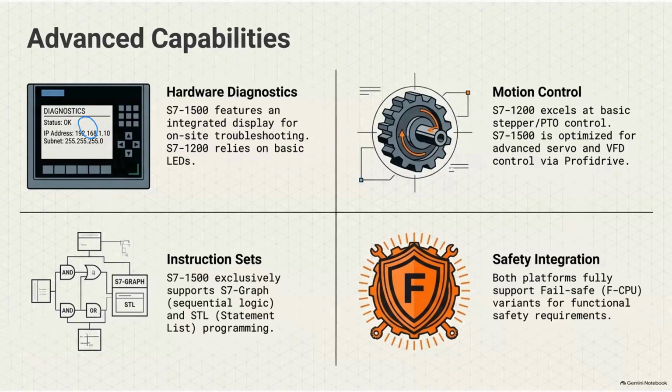Assume a thyristor module that controls a furnace. If the temperature is reaching 1900 or some set point, then PID acts and reduces the output current to the furnace so that the temperature remains constant.